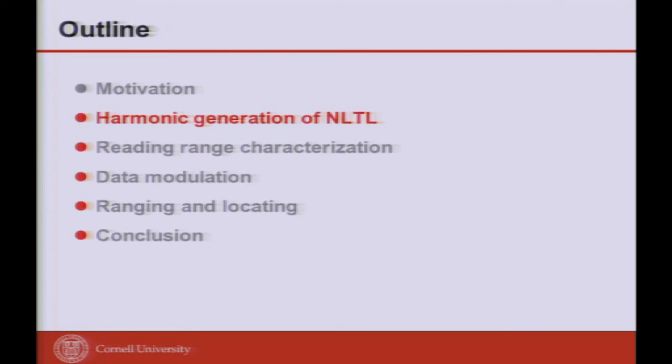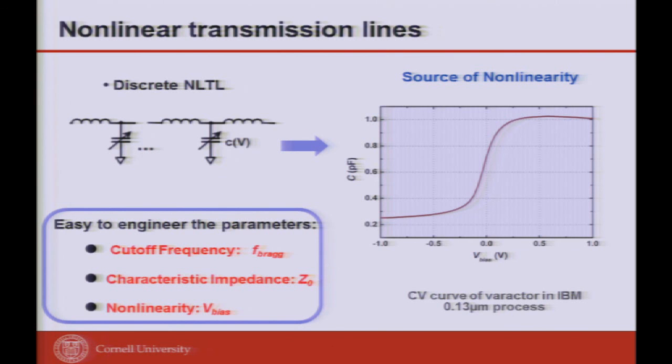I use something called a nonlinear transmission line. In the beginning I did not work on nonlinear transmission lines for RFID. I had my own purposes, edge sharpening, oscillation, generating ultra-wideband pulses and things. All of a sudden, because of a wrong tape out, the student did the layout wrongly. And we measured, and for sure there's no sharpening, none of the things I want, but the harmonic is so big. So I looked at what is so good about it. That was actually the accident, the start of many good properties out of that error.